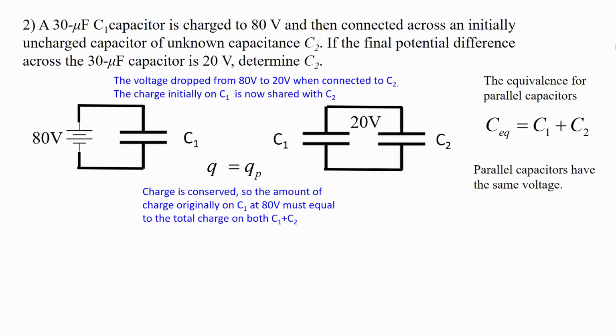And of course, as we know, anything that's in parallel with each other, be it a capacitor, a resistor or inductor, which we'll learn about hopefully before the end of this course, will have the same voltage across each component that's in parallel with each other. That being the case, we can write this in the following way. The equivalent capacitance times V is equal to C1 times V plus C2 times V, being that the voltage across C1 and C2 are the same.